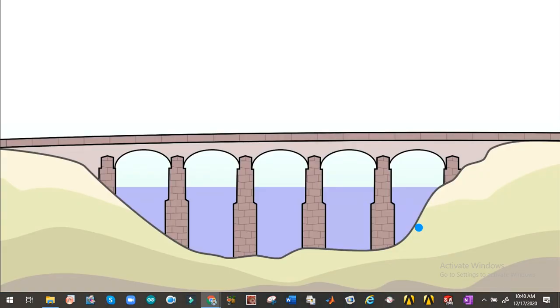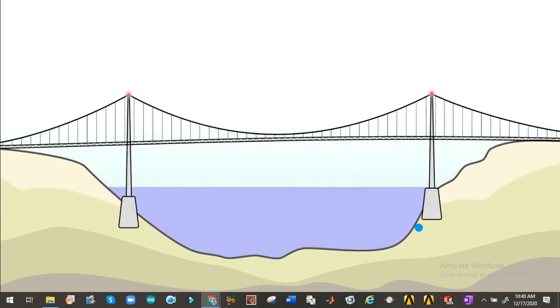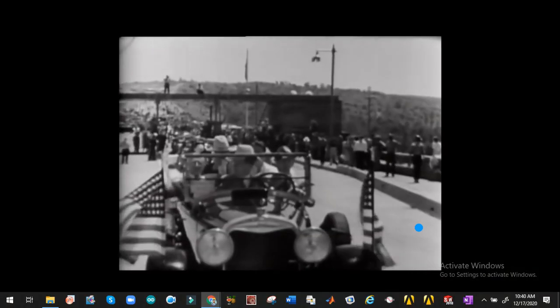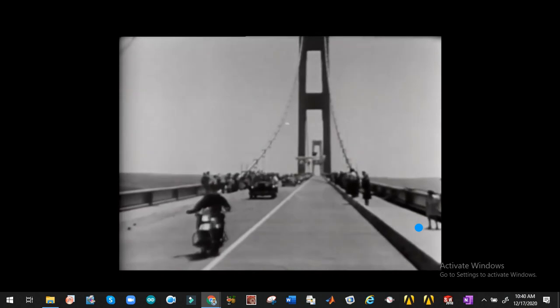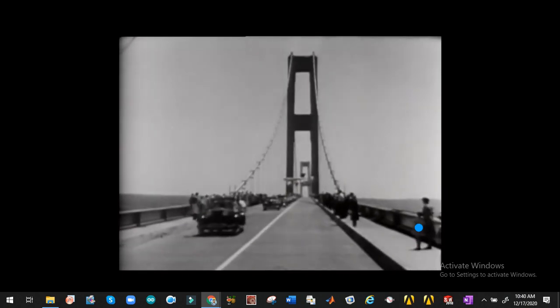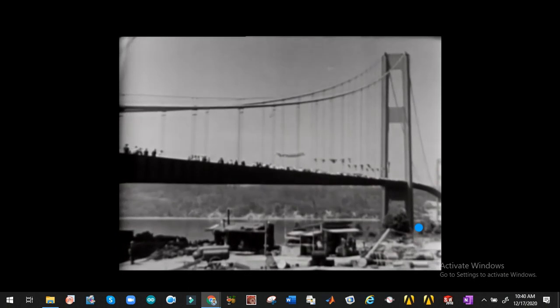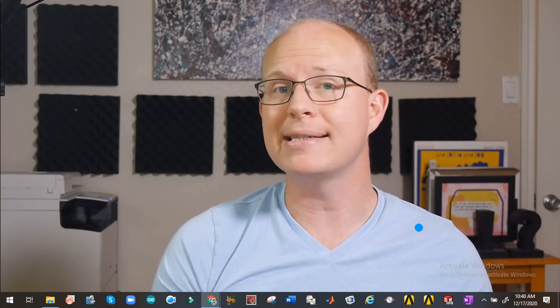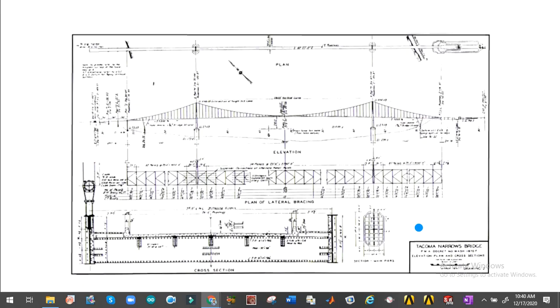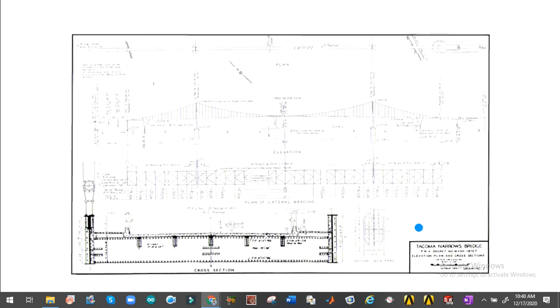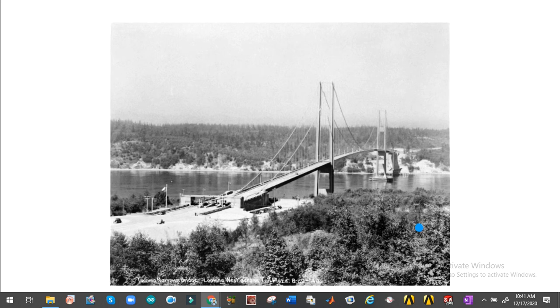Where before bridges were generally stiff enough that gravity was the only load that needed to be considered, now a new force started to impact their designs: the wind. In July 1940, the Tacoma Narrows Bridge opened to traffic between Tacoma, Washington and the Kitsap Peninsula. At the time, it was the third longest suspension bridge in the world. Financing construction of the bridge was a major obstacle, which led the state to pursue an innovative design. Rather than the originally proposed trusses, the bridge used two narrow plate girders to stiffen the deck, giving the bridge its iconic steel ribbon appearance across the Puget Sound.